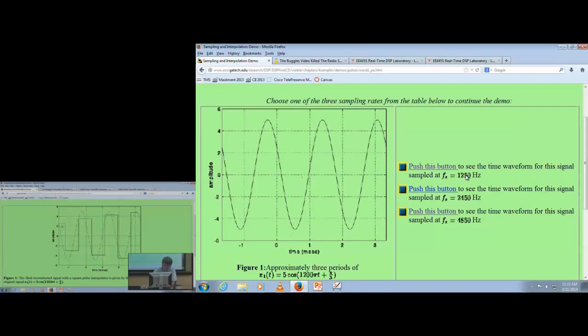That's right, it's a square wave, not a cosine. So it's a square wave with harmonics at multiples of 600. So the analog low-pass filter, if it cuts off at 625, is going to remove all the harmonics. And we'll get a very smooth looking cosine after we pass this through an analog low-pass filter.